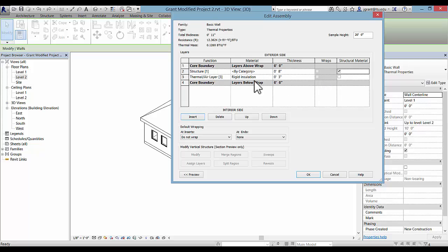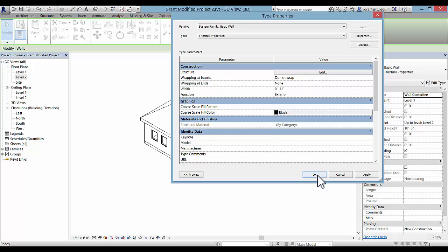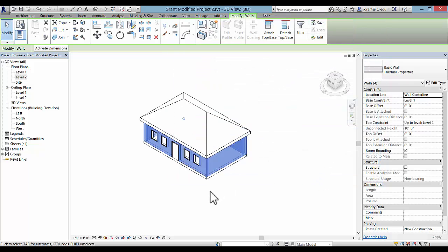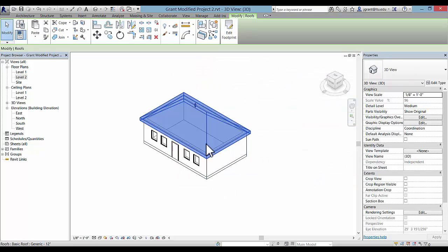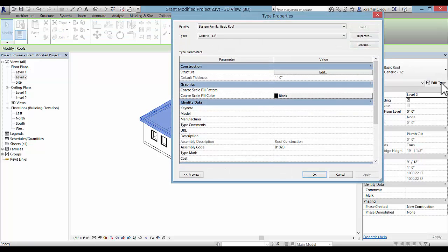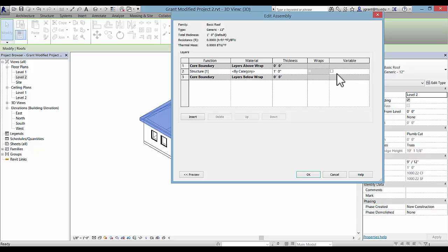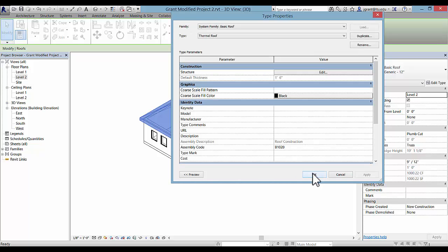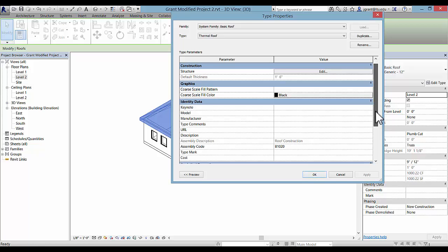There are several underneath the Autodesk physical asset folder in materials, and so we'll do the same thing for the roof. In the first original basic model, we kept everything as defaults, and this one we're adding a lot of thermal properties to the material. So for the roof, we'll do the same thing. We'll insert another layer and pick up a type of insulation that we can use.